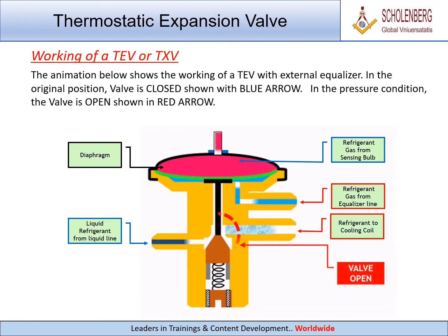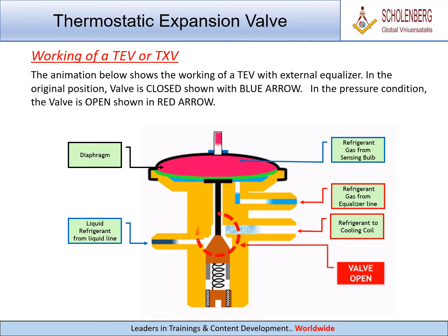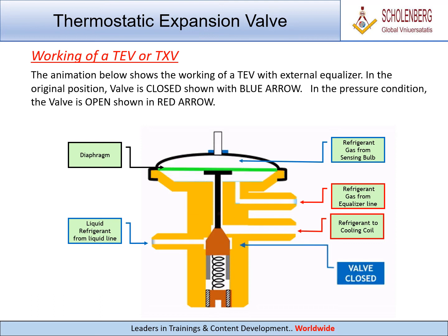Working of a TEV or TXV. The animation below shows the working of a TEV with external equalizer. In the original position, valve is closed shown with blue arrow. In the pressure condition, the valve is open shown in red arrow.